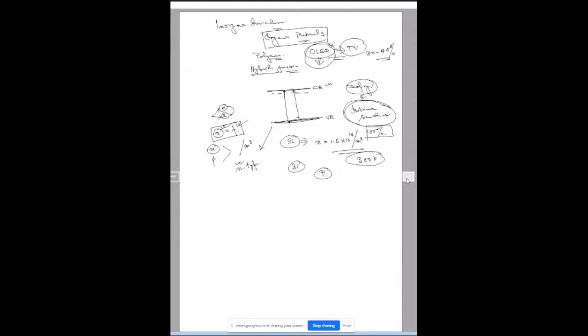So it becomes n-type, and the other becomes p-type if you add a group 3 element. This can be understood very easily. If you put in phosphorus, which is pentavalent, with 5 electrons in the outermost shell, it will replace silicon and share 4 of its outermost electrons with 4 adjacent silicon atoms, and 1 electron will be loosely bound to phosphorus. With a little amount of energy it can be released and go to the conduction band. That's how the phosphorus atoms donate their electrons to the conduction band.